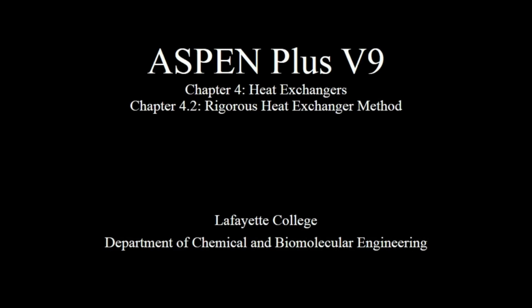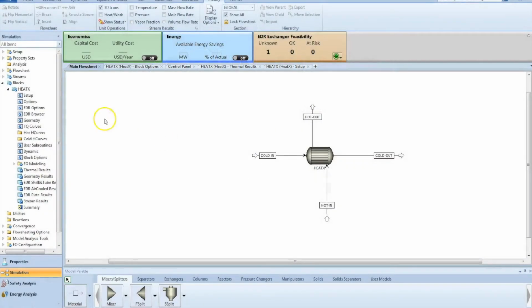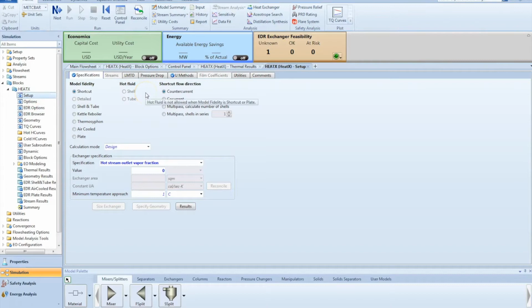This screencast will teach you how to utilize the rigorous heat exchanger method in Aspen Plus software. To begin, open your shortcut heat exchanger method and purge the results by clicking on the backwards blue arrow at the top of the screen.